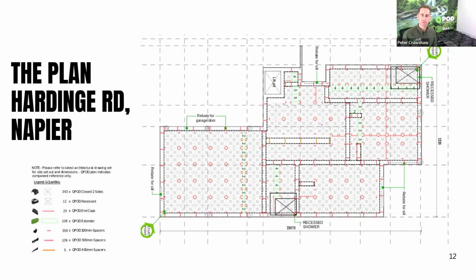So in terms of getting that strength back again in the ribs, it comes down to the steel in the ribs. So you might be looking at more steel than a typical TC1. So you might be up-speccing the steel or going to rib bars, and then right up through into the expansive grounds, medium and extreme, we'll be looking at putting some shear steel in there, whether that be stirrups or fibre in the concrete. Obviously, the latter being the preferred. Hope that answers the question there.